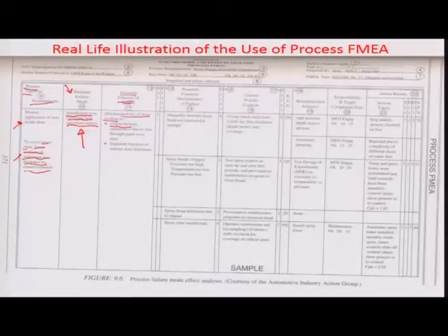There may be impaired functionality of the interior hardware of the door. For example, after a substantial amount of waterlogging for some amount of time, the way that the window regulator is going to move, in placing the window back into place in the window up position or the window down position, that may get impaired because of rust and improper lubrication. Okay, rust actually spreads whenever there is a metal to metal contact. It may also lead to some kind of movement problems related to the door hinges.